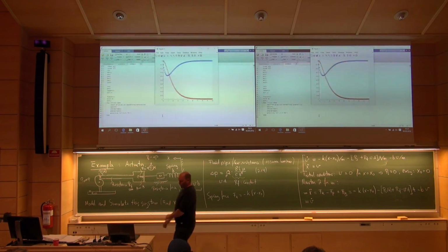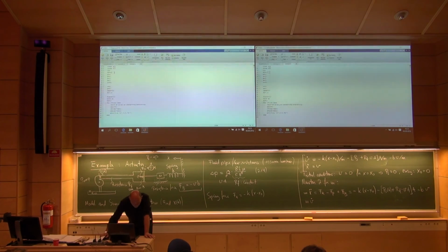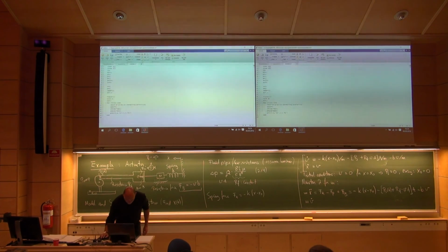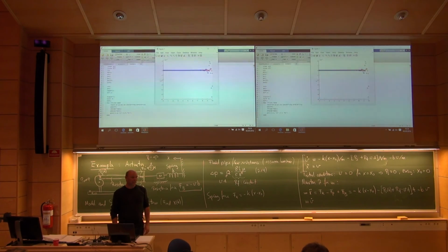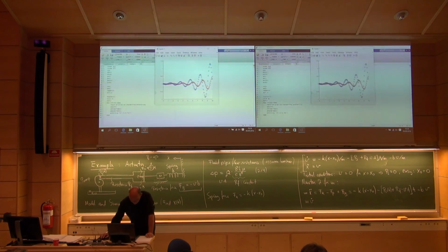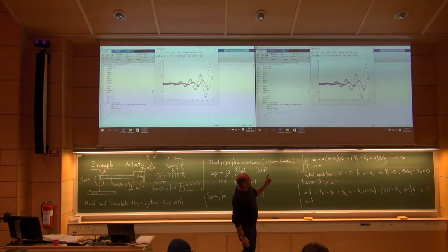Okay. If we want a more interesting solution, we can now start playing around with the numbers. I think I have a nice setup here. The spring stiffness. A spring is normally quite stiff, quite hard. So 100. Then what's going to happen? It blows up. Then my delta t is obviously too big here. So now we have much faster dynamics in our problem. But we can smooth it down a little bit. We take a bigger mass, 10 kilos. Yeah, that helps a little bit. Still, we shouldn't get such complicated solutions. I'm not sure if I believe it.